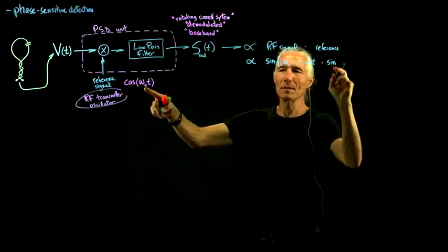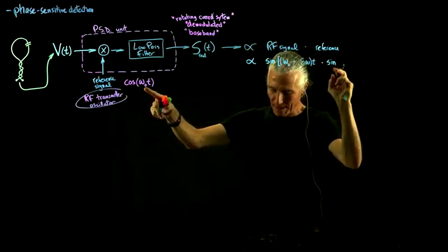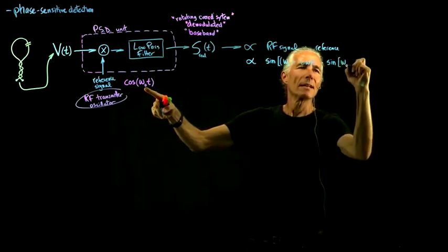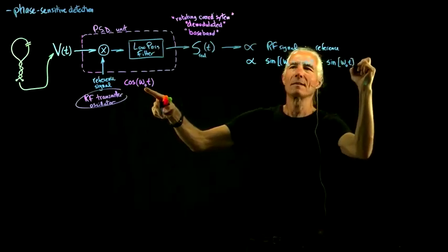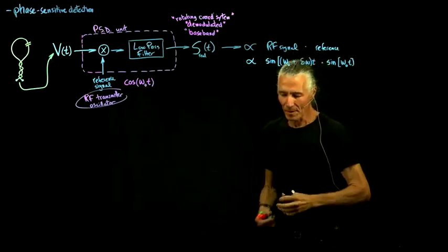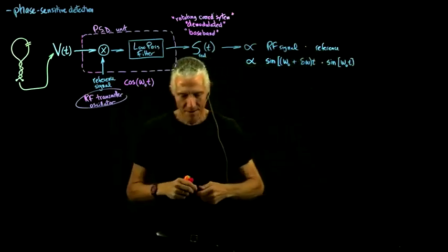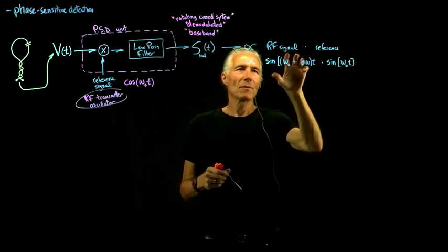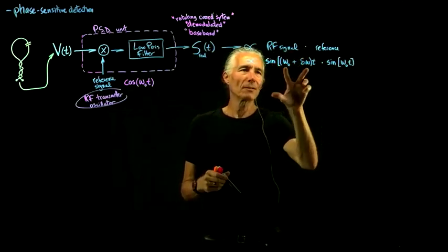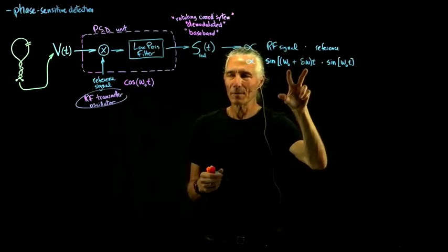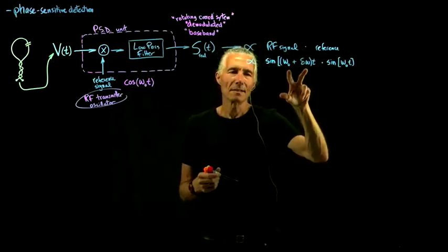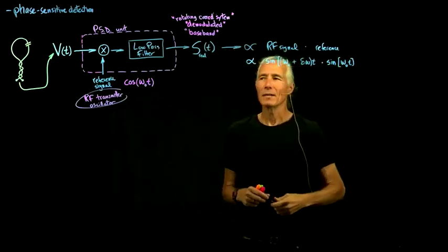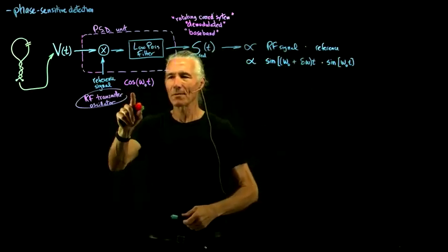So we're multiplying by a sine here, and that's just the center frequency. Okay, so that's what we're doing sort of mathematically here. Taking our signal, which doesn't necessarily have to be the same frequency as the transmitter, and we're just simply multiplying it by a sine or a cosine.